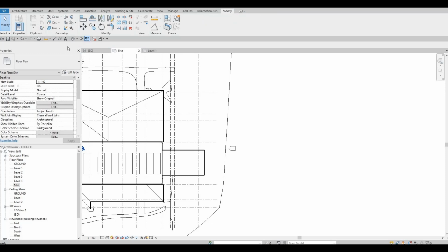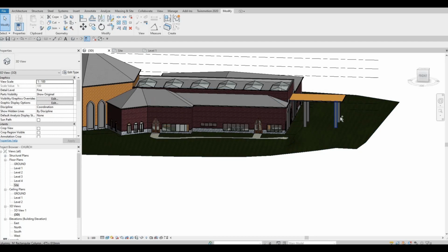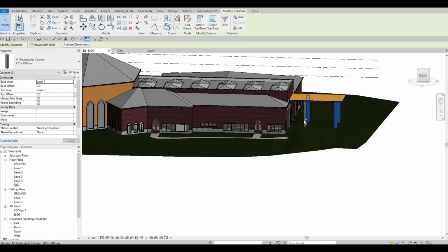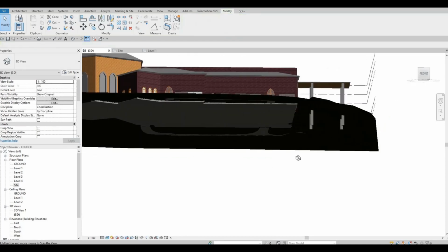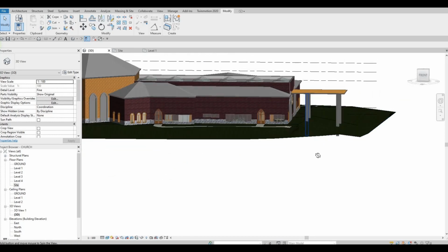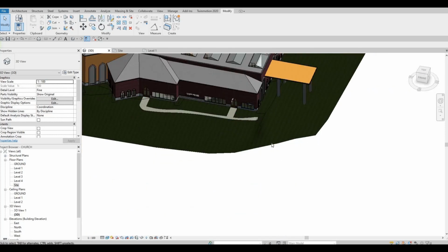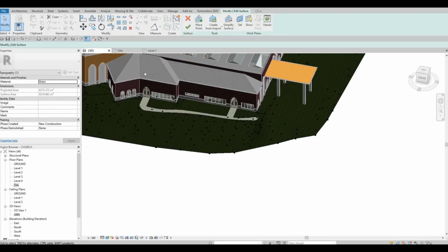And then let's look at it in 3D. So there is a big drop, and then here on this post I'm going to put this one in ground, and then base offset negative, I'm just gonna shoot it at 2000 for now, so that it's protruding way down, and at least we could set up right here. So now what I'm gonna do again is edit surface,